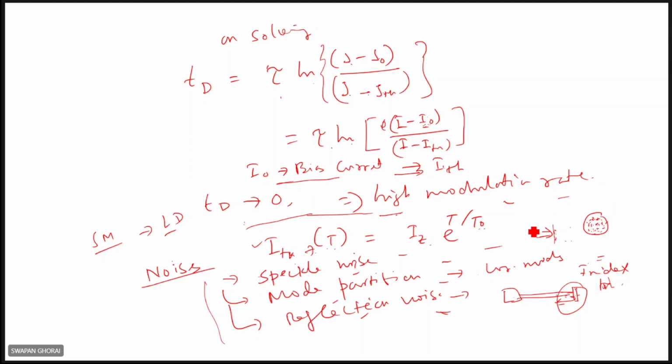How does speckle arise within the fiber? Suppose laser light is launched and propagating in a fiber. Now, if there is a break, or a different medium, or a connector or splice, then this speckle noise will be created. And this will degrade the signal to noise ratio. That is the speckle noise, or the coherent noise.